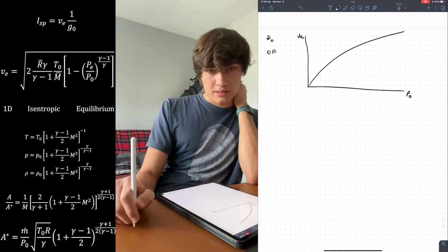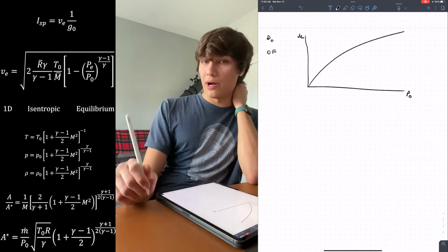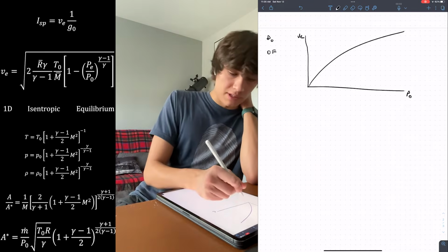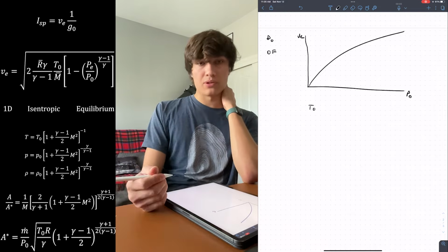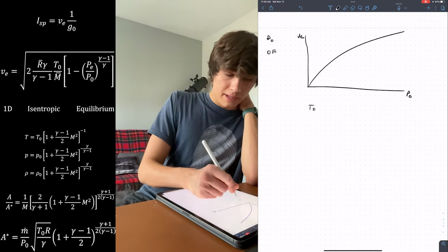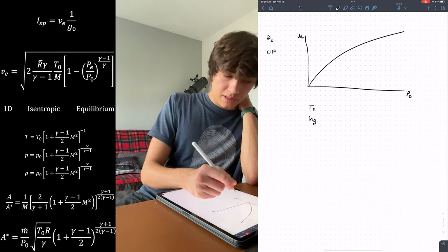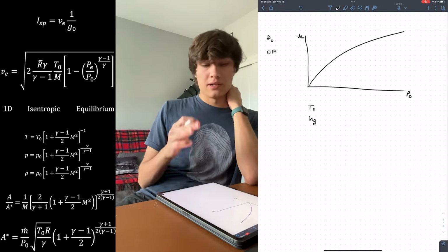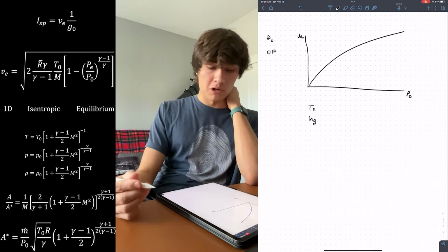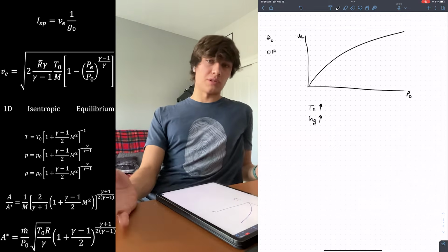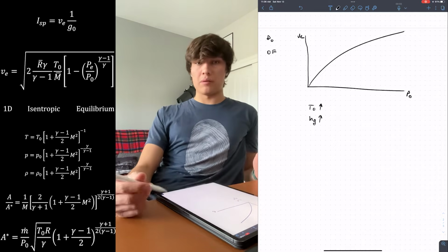Increasing the chamber pressure increases combustion efficiency, but it also increases the heat flux into the engine by increasing both the combustion temperature and the convective heat transfer coefficient from the gas to the chamber wall. And it also increases the hoop stress on the engine, making the material requirements harder.